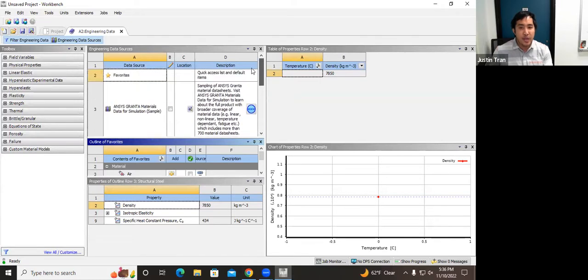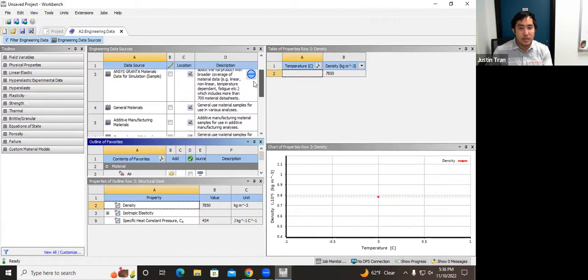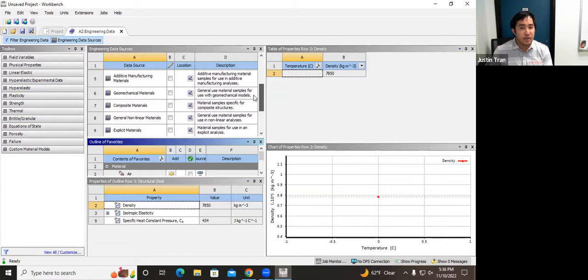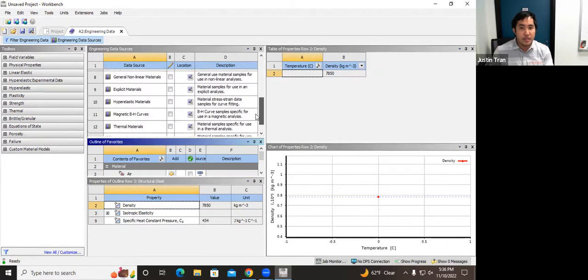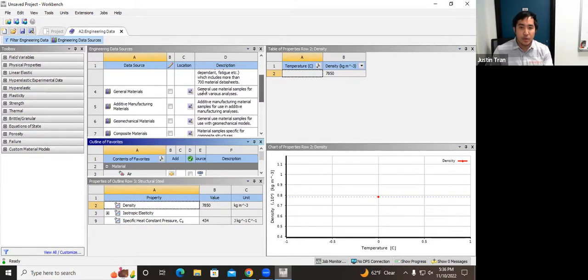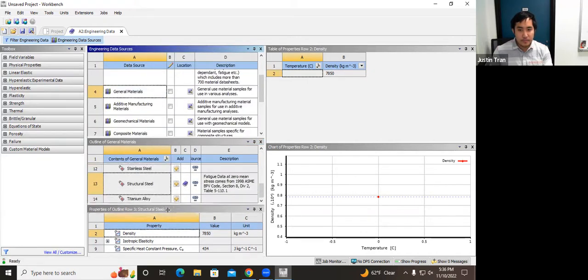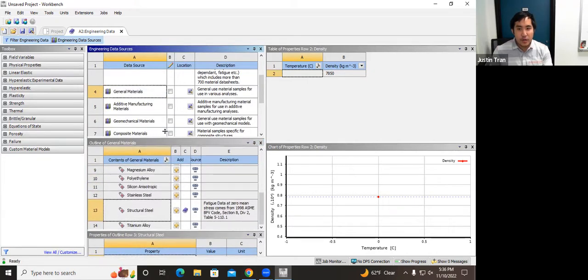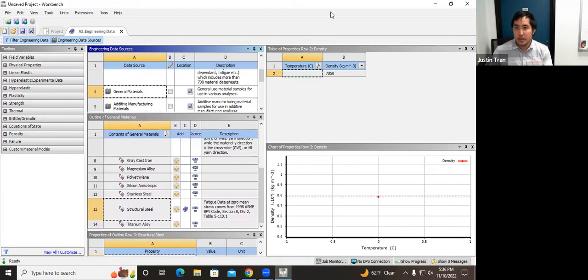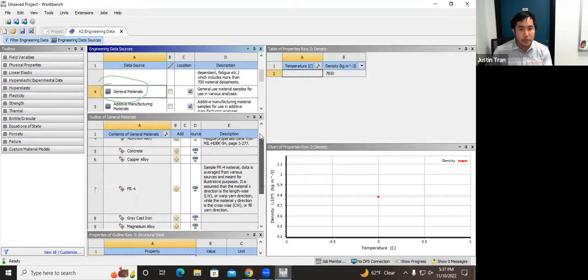Okay? And so what we have here are ANSYS granted materials, general materials, additive manufacturing, geomechanical, composites, and a lot of stuff. Okay? So we're going to go under general materials. And so we're going to click on that. And then after you click on general materials, actually, let me go ahead and circle that. And so after you click on general materials, this window in the middle here is going to change here, right? And so under general materials, you'll have all these different metal alloys that you can choose from.